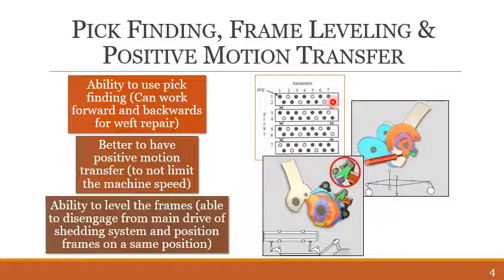Another ability included along with pick finding is the indication of the current pick that is being inserted. For example, if a 3 by 1 twill is being made, a machine can indicate which pick out of the 4 is being inserted. When we move the machine forward or backward for pick finding, it indicates which shed is being opened out of these 4 picks. This is possible through the digital displays available with machines these days, which can indicate which shed is open for which pick.